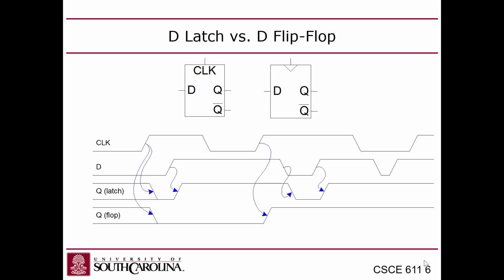Both of them have a clock input. So, clock. You're in a CPU. The data paths are driven by the clock. They're moved forward. They're evaluated in each clock cycle. So the clock, and we'll talk about this a little later in the lecture, but the clock period, the clock speed, is determined by the maximum propagation delay of your logic in the system.